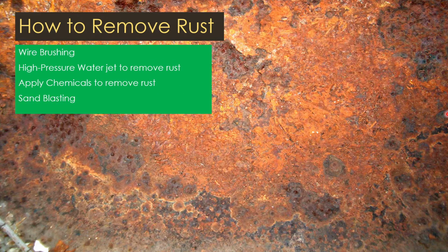How to remove the rust? Before doing any treatment for the metals, we have to remove the rust. That is, cleaning the metal shall be done before any kind of treatment. Wire brushing, high pressure water injection, applying chemicals, and sandblasting are some of the common general methods used in construction. These can be used in other industries also, and widely in any type of scale of work.